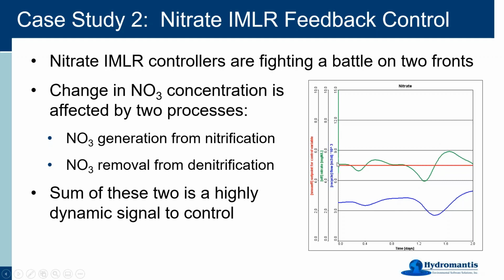Well, what's the difference between what happened here and here? The reason is because this is sort of in the night when the loading went way down. And so therefore, we just did not have as much nitrate being generated. And so therefore, the controller said, oh, well, nitrate's going way down, I need to back everything off. It actually didn't have as much to do with the recycle as it did with the fact that the loading was different. So that's a really interesting aspect of that controller behavior.